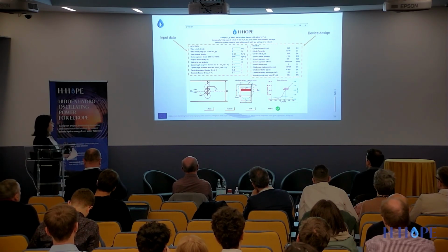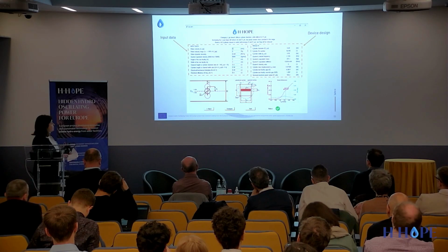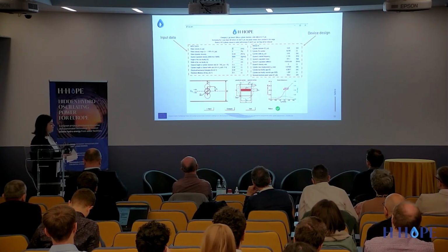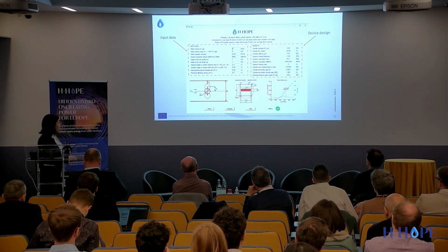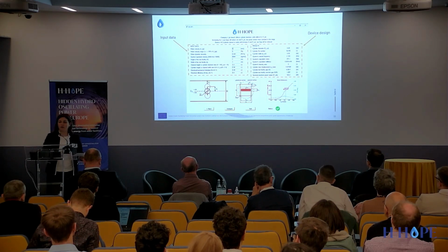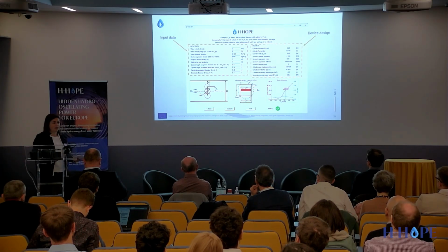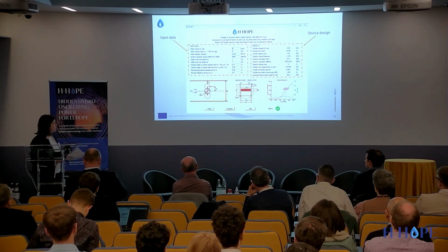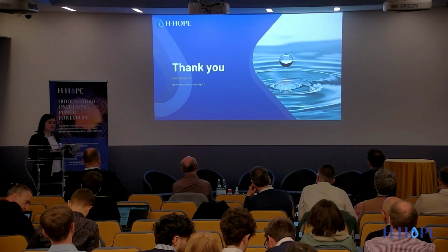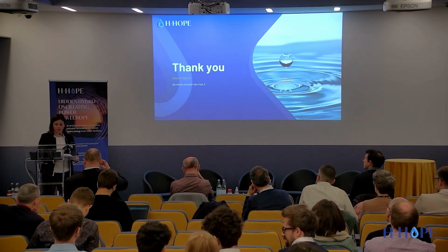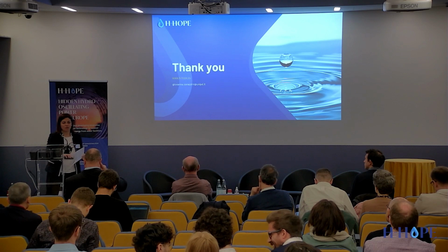So with high velocity, 2 meters per second, and a channel that is 1 meter and has a width of 1 meter, so quite big. It's not a piping application. And in this case, the power that can be extracted is quite important, roughly 150 watts. Not milliwatts, but watts, so real power. It's not big hydropower production, but it's useful to feed sensors. So this is all. This is the outcome of our work package 4 on the design. And this is the starting point of our discussion.